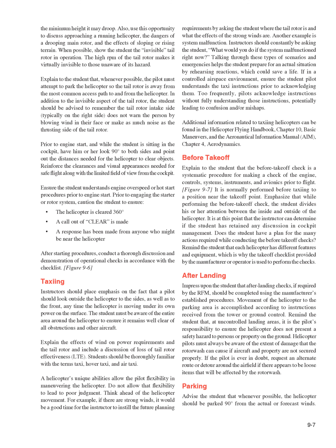Students should be thoroughly familiar with the terms taxi, hover taxi, and air taxi. A helicopter's unique abilities allow the pilot flexibility in maneuvering the helicopter. Do not allow that flexibility to lead to poor judgment. Think ahead of the helicopter movement. For example, if there are strong winds, it would be a good time for the instructor to instill the future planning requirements by asking the student where the tail rotor is and what the effects of the strong winds are.